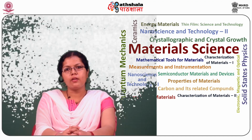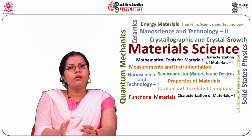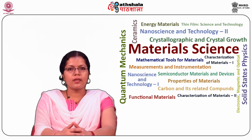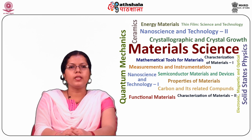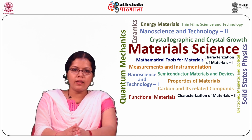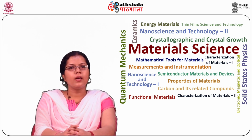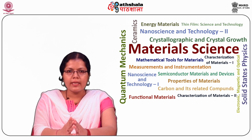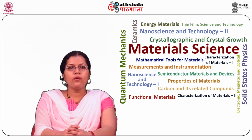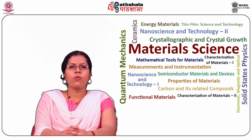It consists of two coils which are connected in different circuits for measurement of power. The fixed coils or field coils are connected in series with the load and so carry the current in the circuit. The fixed coils therefore form the current coil of the wattmeter. The moving coil is connected across the voltage and therefore carries a current proportional to the voltage. A high non-inductive resistance is connected in series with the moving coil to limit the current to a small value. Since the moving coil carries a current proportional to the voltage, it is called the pressure coil or voltage coil of the wattmeter.